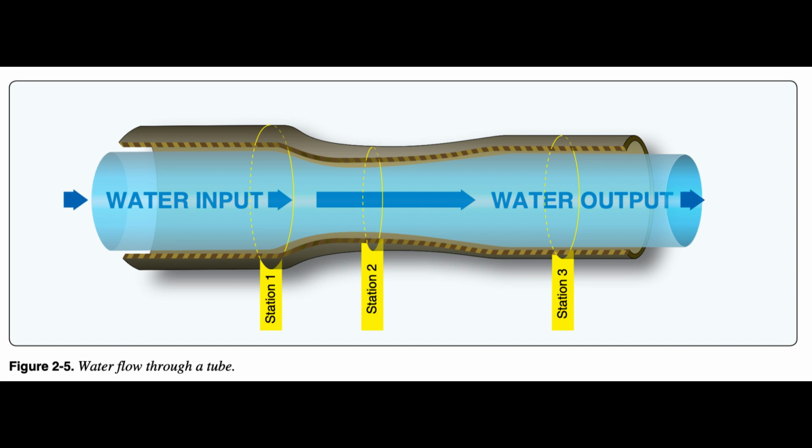Specifically, in this case the energy referred to is the dynamic pressure, the kinetic energy of the air, more velocity, more kinetic energy, and static air pressure, potential energy. These will change among themselves, but the total pressure energy remains constant inside the tube. A simple tube with a constricted portion near the center of its length illustrates this principle. An example is running water through a garden hose.